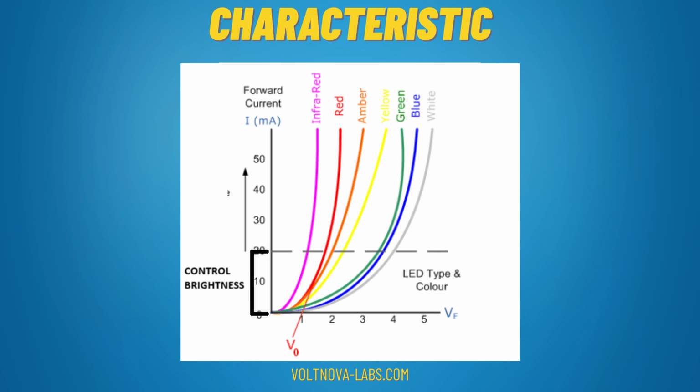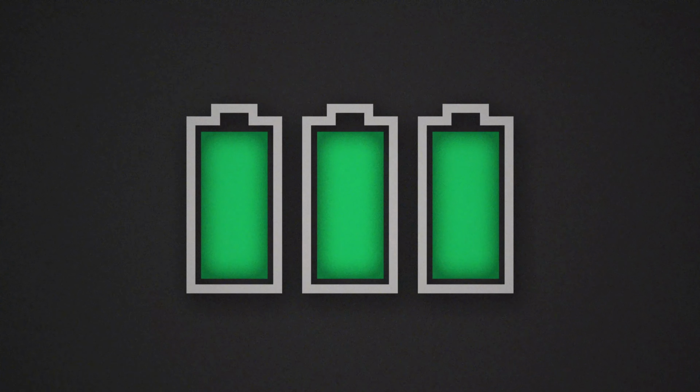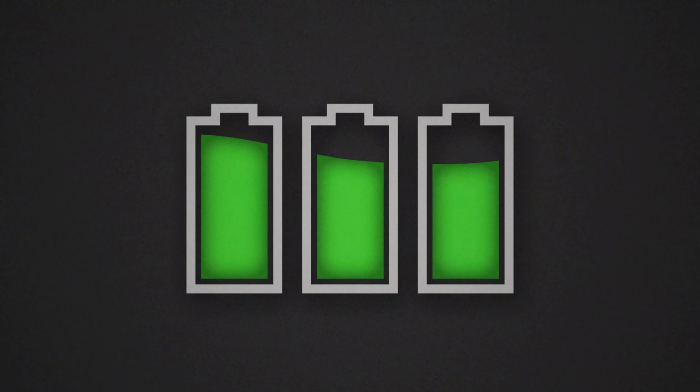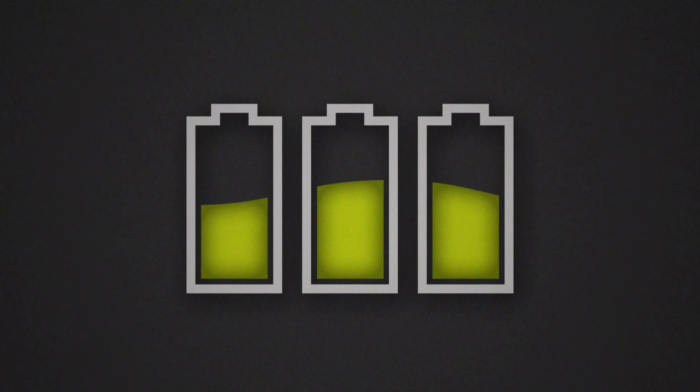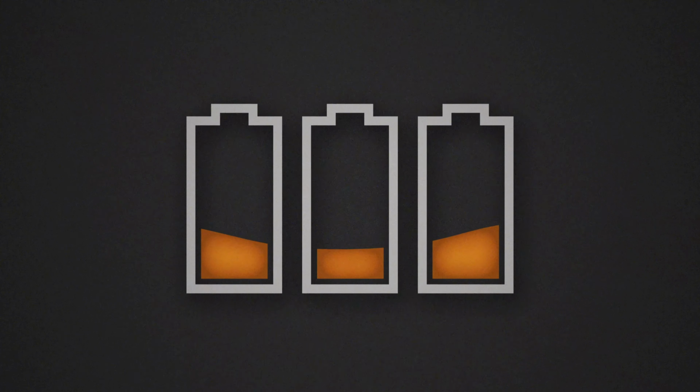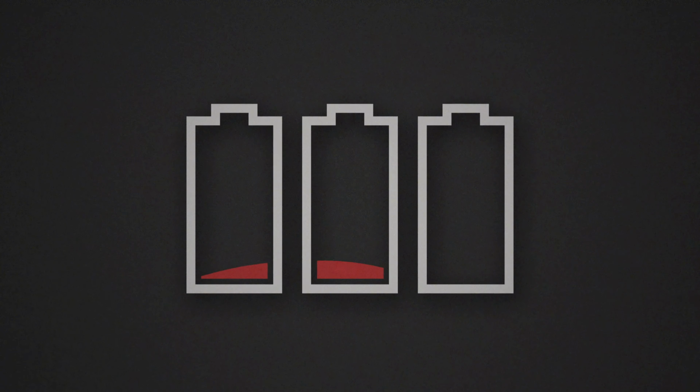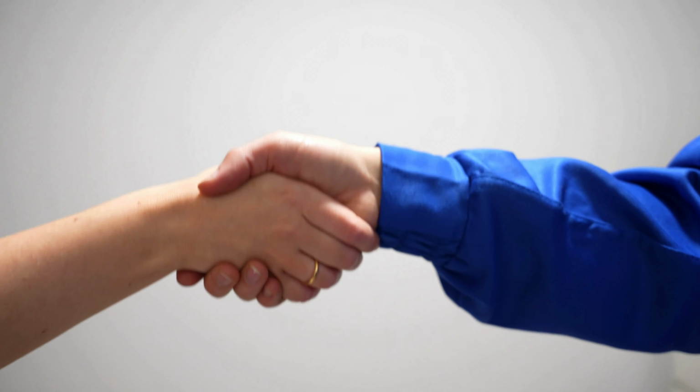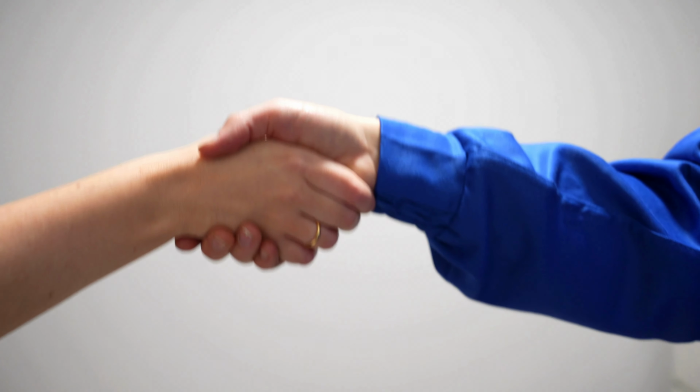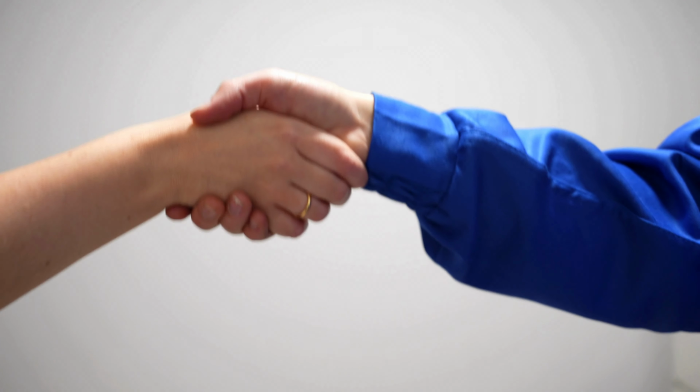That's why we need to stay between 1 milliampere and 20 milliamperes, depending on approximately what brightness we want to achieve. The other thing is that the more current flows, the more current will be drawn from our battery, and we don't want to drain it quickly. So we need to find a compromise, right? Now, if you are curious about what will happen if we exceed the threshold voltage and, for example, power the LED directly, I will gladly show you.